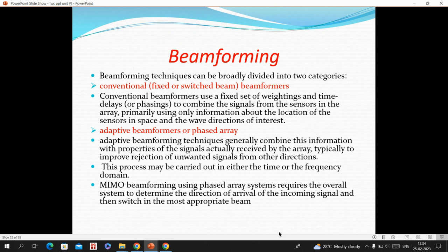If the precoding is done at an earlier stage, and after the precoding some further processing is done in the form of digital signals before finally transmitting the information, then it is called digital beamforming. Either way, beamforming is used to focus on the user and radiate the maximum power in the required direction. That is the concept of beamforming.